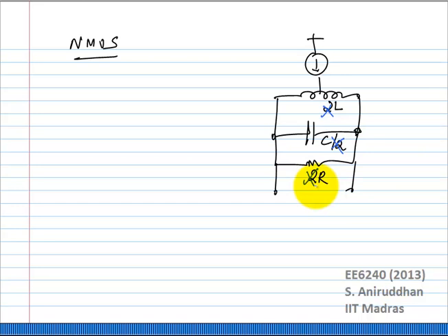Oh, but now let us say I compare it with this particular case. Okay, let us say you're right, the conditions were different because I was using a center tap inductor in one case, I was using two RLC tanks. We said we can make it a single RLC tank using a center tap inductor. And then I also said you can normalize it back to the same value of inductance also, because really the frequency of operation depends on 1 over root L times C. If I increase C, I can cut down L and get the same oscillation frequency.